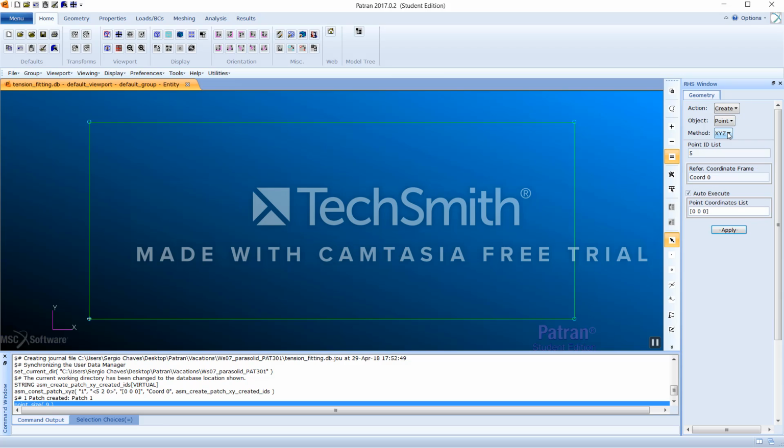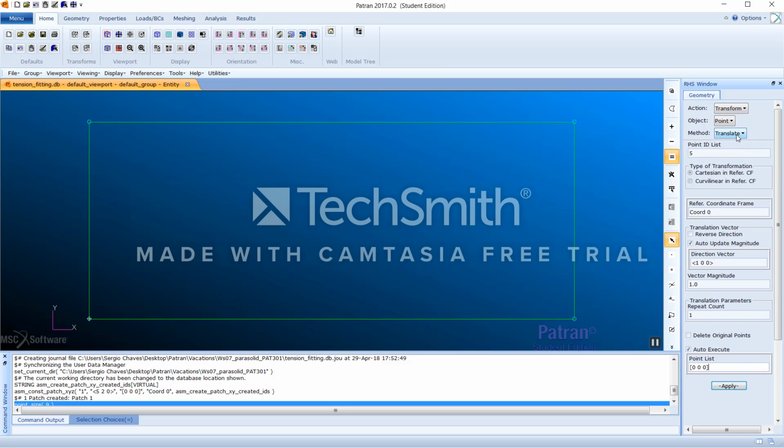In this step, we're going to copy 2 points at opposite corners. Set the action as transform, object as point, and method as translate. Enter 0.5, 0, and 0 for translation vector, and select the top left corner point and apply it. Then enter 0, -0.5, 0 for translation vector and apply and select the bottom right corner and apply it.